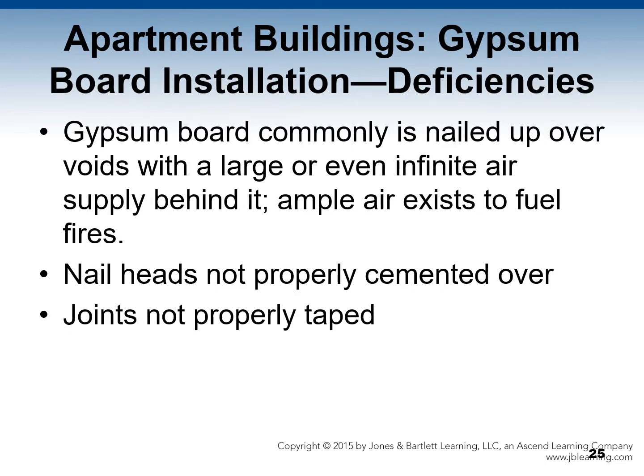With gypsum board installation, it is commonly nailed up over voids with a large or even infinite air supply behind the board. In other words, ample air exists to continue combustion. Nailheads often are not properly cemented over. They must be, otherwise they heat up and cause problems. Very often the joints are not properly taped. Nothing is ever added for an extra margin of safety.